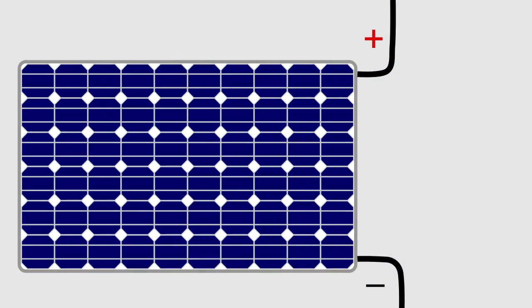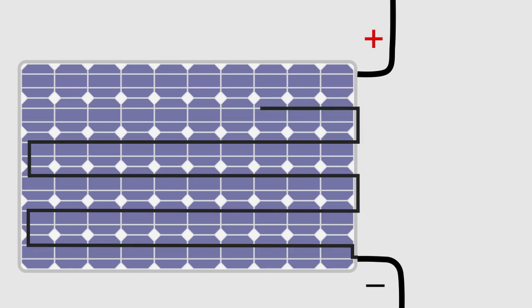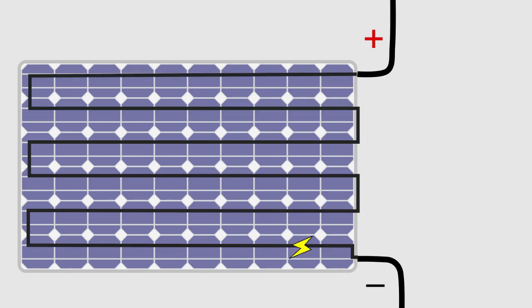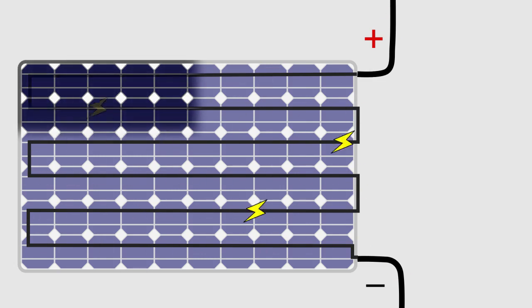The next thing to consider is what happens as current flows through a single module as well as through an array of modules. Recall from the first course that modules consist of numerous solar cells wired in series, so we can think of the electrical current as running throughout the whole module cell by cell by cell. This extends to each module being connected in series as well. Any single cell or module that stops producing current becomes an electron sink rather than an electron source. This might happen when a module is shaded or otherwise faulty. This interrupts the continuous movement of the electrons, which decreases the operating current of the module or the array.